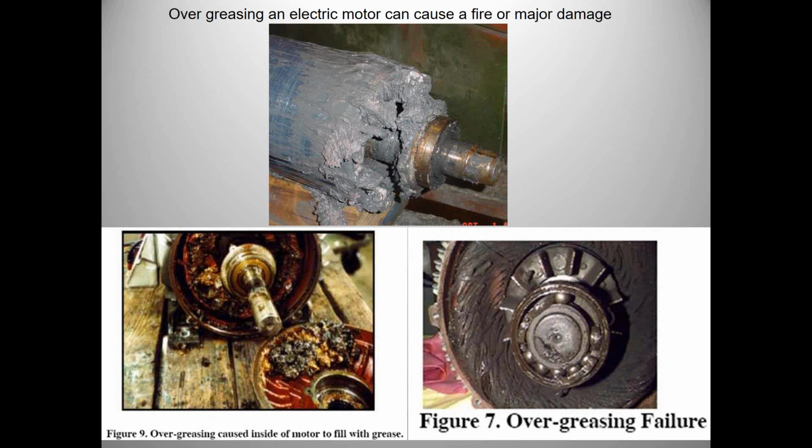Here, just a lube practice. A simple lube practice of plant grease and electric motors. You can see the one in the lower left-hand corner was at a motor shop. The motor failed because of over-greasing. The top one here, not training a new maintenance person well enough. The PM said, take the bottom plug out of the motor and pump grease in until you see clean grease come out of the plug. Well, in this case, not being trained or not using common sense, after pumping a whole tube of grease into this motor and the grease not coming out, it caused the motor to fail. So again, can you have failures just with your maintenance practices? Yeah, possibly.